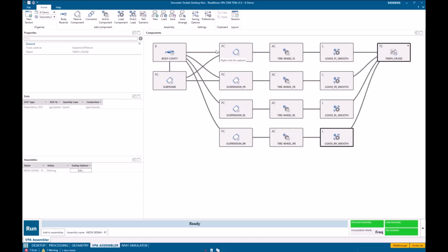Where the suspension is connecting right to the body, that's where the strut mounts are connecting directly to the body, or in the rear, there may not be a subframe, and those suspension components are connected directly to our body. However, in the front, you notice our front suspension also connects to the subframe before it gets connected to the body. So this is the real path for the lower front suspension attachments. They go into this subframe before they go into the body.